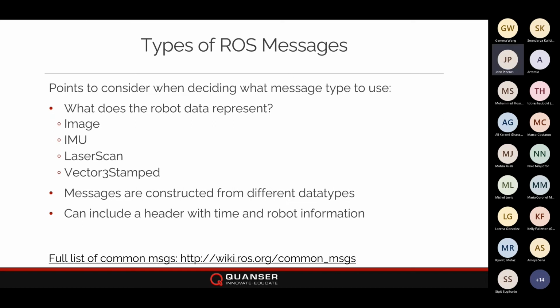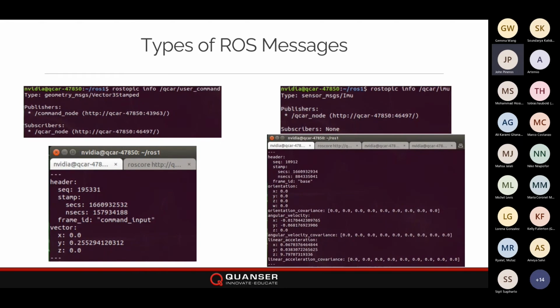And so, because these are common examples out there, odds are you might not be able to get what you're looking for. So, the ROS community also gives you the ability to create your own message using different data types. And so there's this flexibility of you being able to use what's already available or generating your custom messages. There's a full list. I've added a link here under the ROS wiki under all the common messages. This can be sensor messages, navigation messages, so you don't have to construct anything from scratch if it's already available for you.